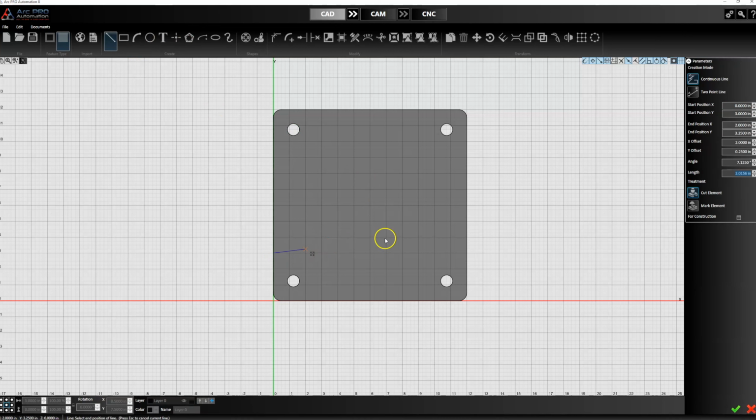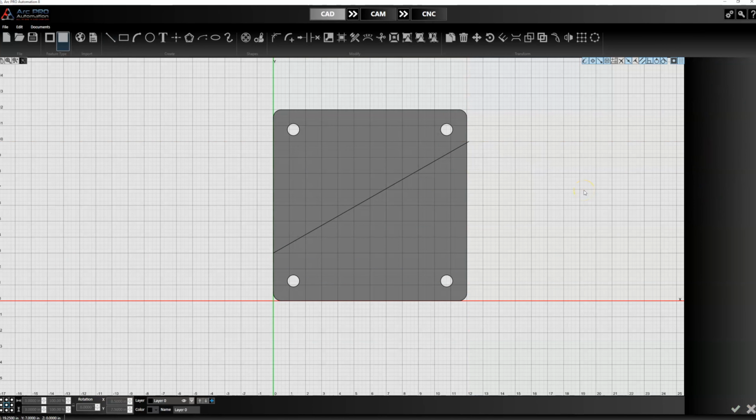Well, you can go ahead and click on one edge and drag across, and you can designate an angle by hovering out here. Notice on the right hand menu it's 14 inches. I would say just make it longer than the part. So let's do 14, click Tab. Now I'm going to go to angle, and now I can designate an angle. See how this is locked in at 12, and then as I drag it, it just sweeps around that point. So now I can say, okay, I want this angle to be maybe 30 degrees. So 30, enter, and then click enter one more time, and it converts that to a solid line.